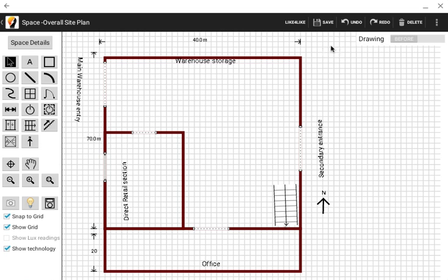Delete. Now, down here, you can turn off snap to grid, which basically just allows you to be more accurate with the drawing. So you can see I can very accurately move the wall around, but if you hit snap to grid, it's going to jump sections to allow you to get it horizontal or vertically more easy. Also, you can have the option to turn the grid on or off, depending what your preference is.